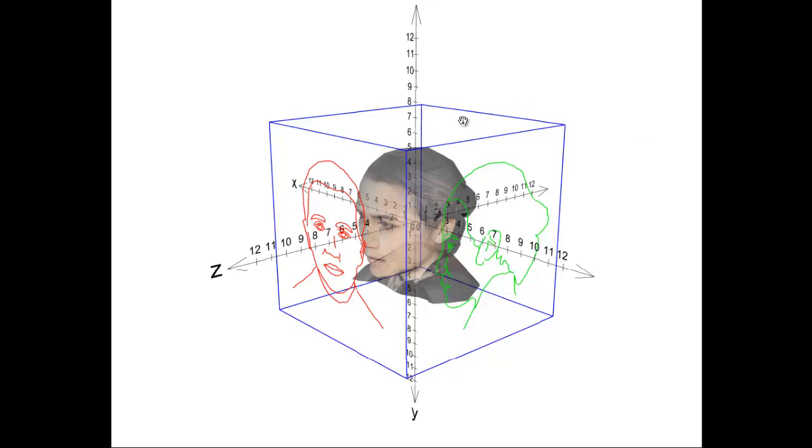If I folded this up, I'd see the top of the person's head up here, the front. If I pull this out flat in this direction, just imagine this is a hinge and we open this flap up, we'd have the right side view, the front view, and the top view. Suddenly we're able to look at a top, front, and right side view on a single sheet of paper or a computer screen and visualize what this person might look like.